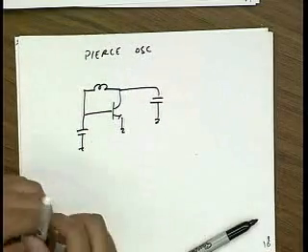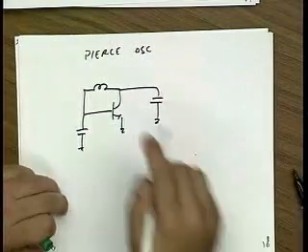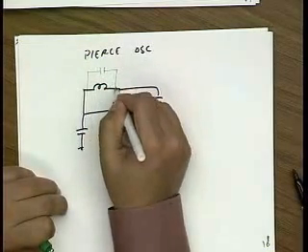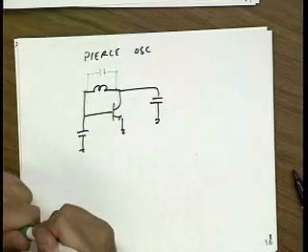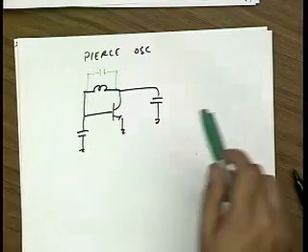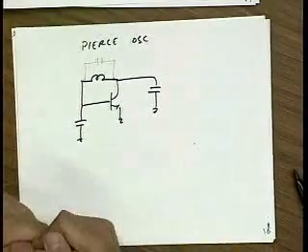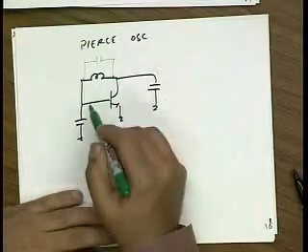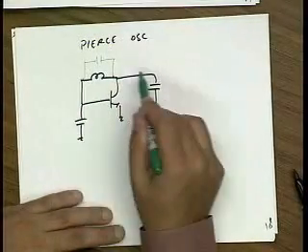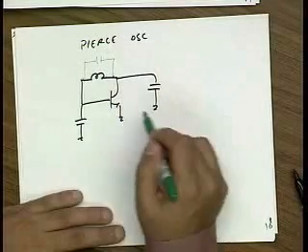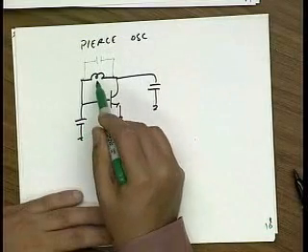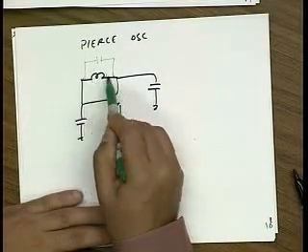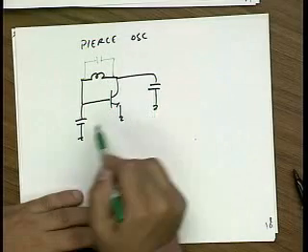And remember, there's also this capacitor across the tank. Well, if you notice, what happens if I get rid of this capacitor? Will the circuit still work? In fact, it does. What happens is that from an AC circuit perspective, you can think of this as one series LC tank, or if you like, a parallel tank with this inductor in parallel with the series combination of